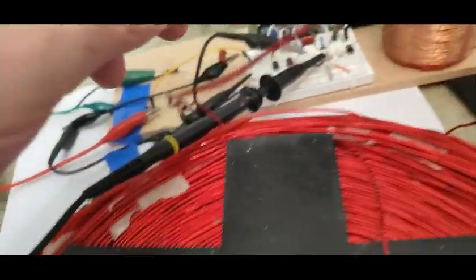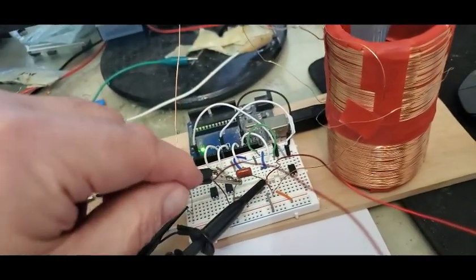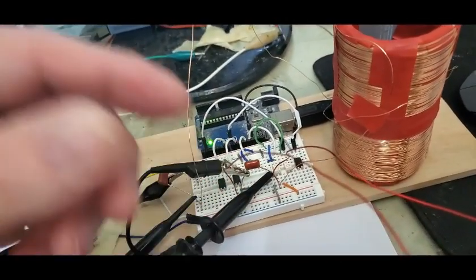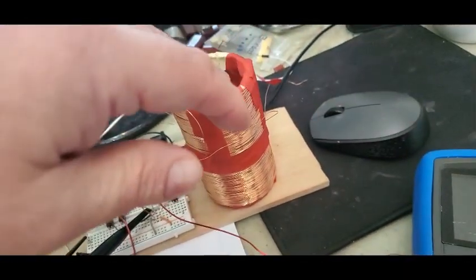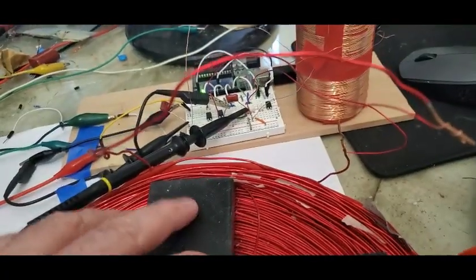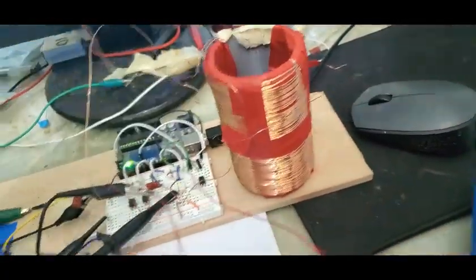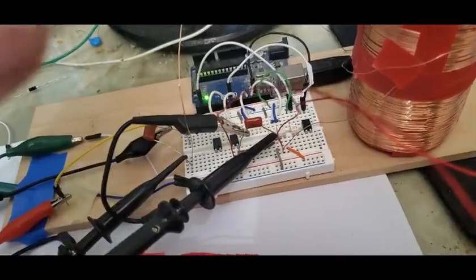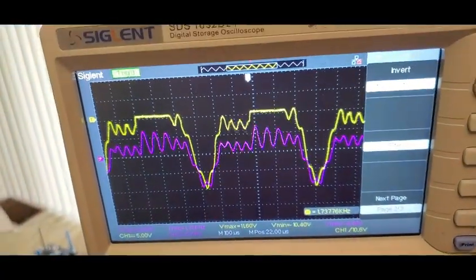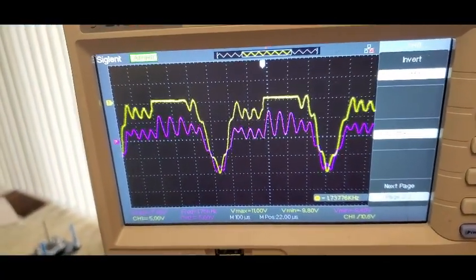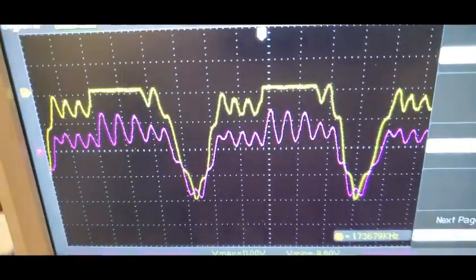So this is kind of silly, but I just took this 10-pound coil and hooked it up so that we discharged this across the 10-pound coil. And I did that because there's going to be a tremendous mismatch in induction between here and here. This is like 70 or 80 and this is like 12, so they're nowhere near matched, and this is fairly high Q. So the first thing we see is it looks like that, which is not pretty, but it's not bad. That's like a little over 6 volts there.